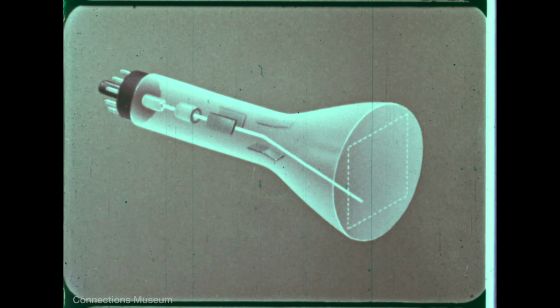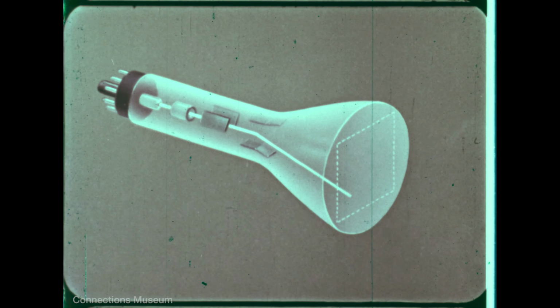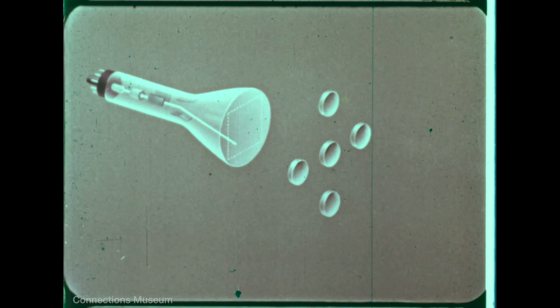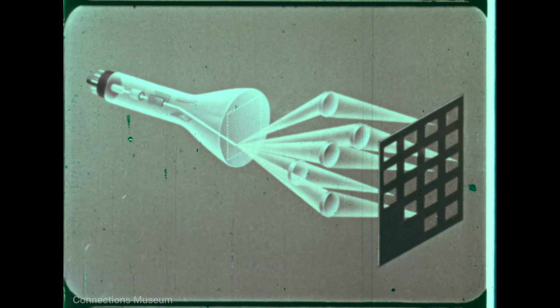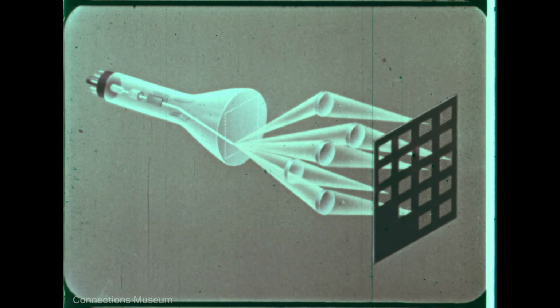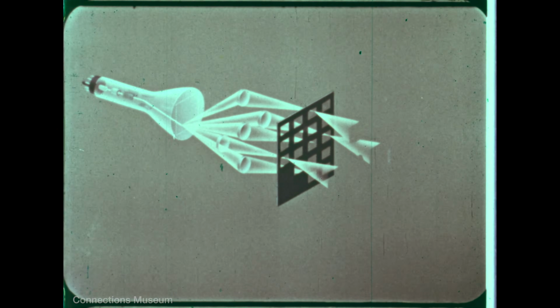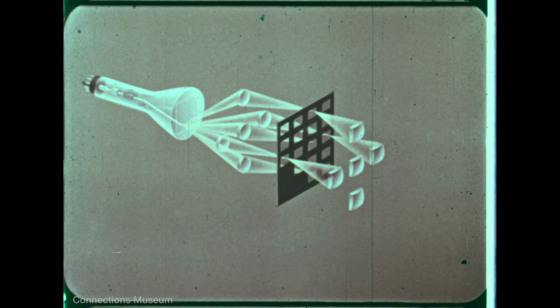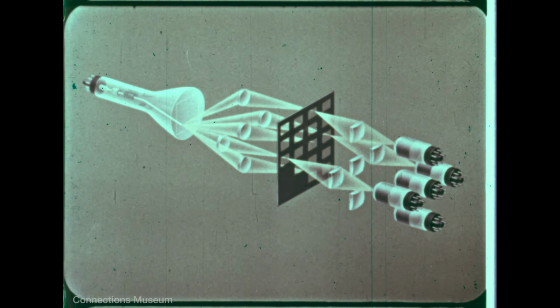The electron beam is directed to one address position on the face of the cathode ray tube. Lenses focus this spot simultaneously onto the same address in all of the storage areas. The light is stopped by the opaque addresses and allowed to pass through the transparent addresses, through another set of lenses, onto a bank of 68 photocells.